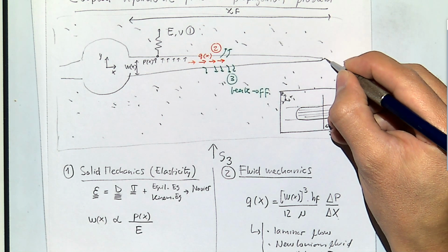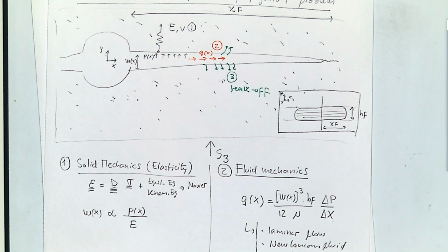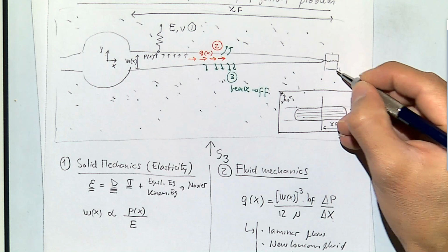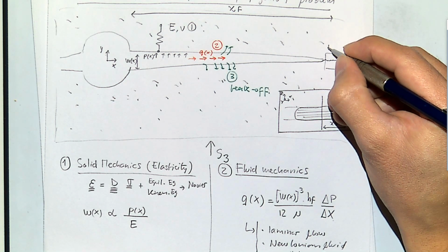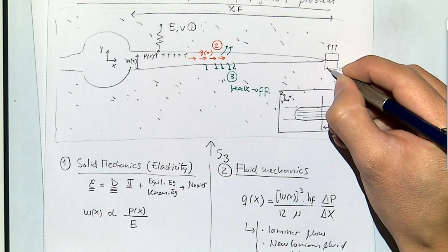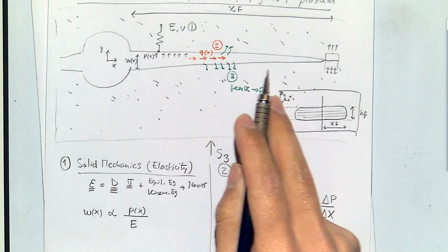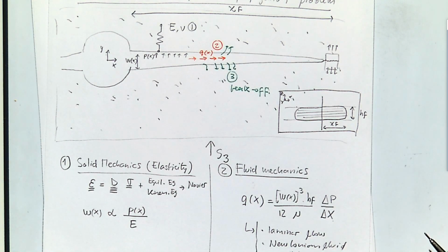In order to break it, we have to split the rock. And this is going to take some energy, breaking the rock. We're going to see that at the tip of the fracture, opposite that on the wall of the fracture, instead of having compression due to the fluid that is opening the fracture, at the tip of the fracture we're going to have tension.